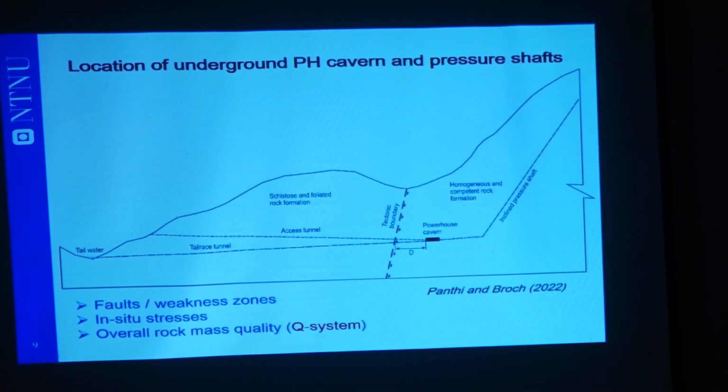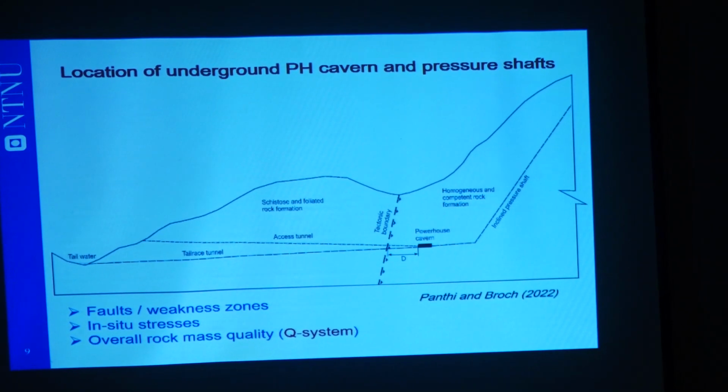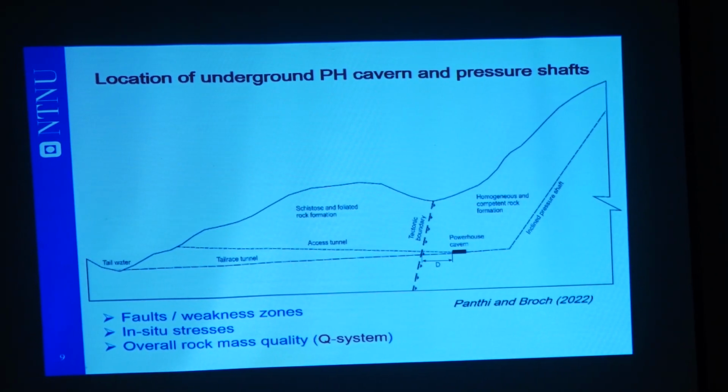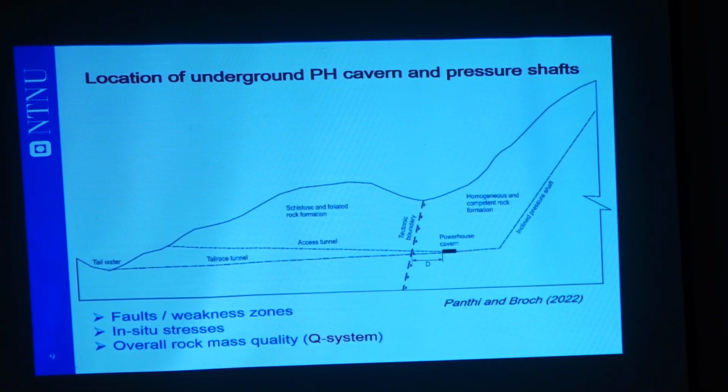Then we should achieve the minimum distance that is required. That can be fixed with numerical modeling. What is important is how the numerical zone needs to be considered very well. In situ stress information will need to be measured here. Once we cross this area, we can do 3D stress measurement to have all 3 tensors of the in situ stresses, and that will be helpful to do the stability assessment of the underground power station, so that we achieve the minor principal stress more than the static water pressure if we would like to have an unlined pressure control system.